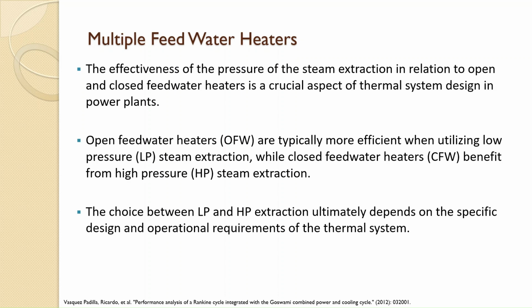Usually, open feedwater heaters are more efficient when utilizing low pressure or LP steam extractions. On the other hand, closed feedwater heaters benefit from high pressure steam extractions. Open feedwater heaters operate on the principle of direct contact between steam and feedwater, allowing for efficient heat transfer. So the use of low pressure steam is advantageous because it can effectively raise the temperature of the feed water without complexities associated with higher pressures.